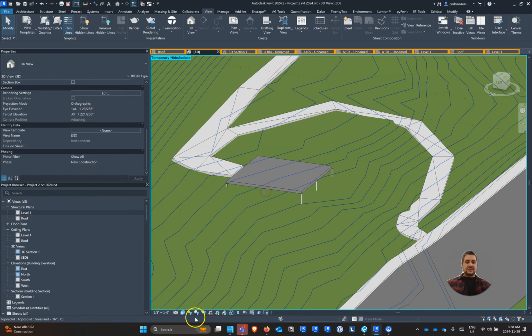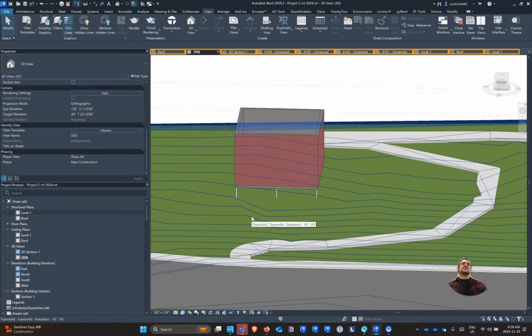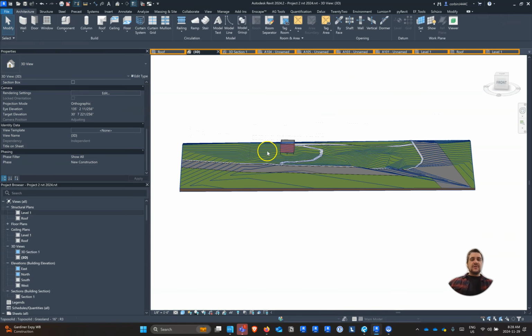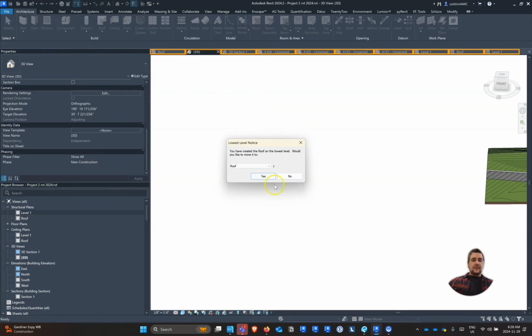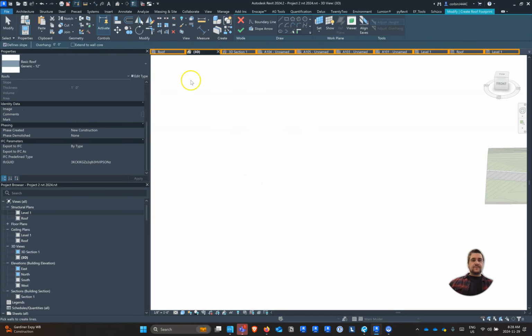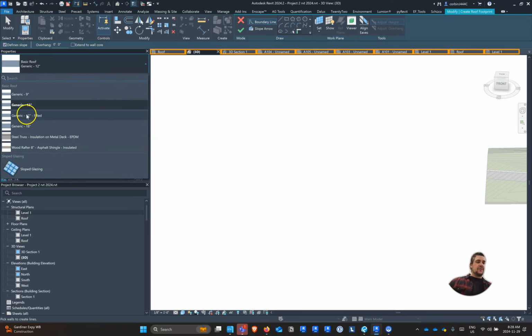So we have our columns placed. The next little thing is, I know a lot of you want to start doing some interesting roofs. And so with a roof design, there's a few different things we can do. So, and I might just move over to the side here. If we click a new roof here, and we click OK, there's a few different roof types here. I think the first thing we can do is making sure we select a roof thickness and type that's emblematic of what we're trying to do.